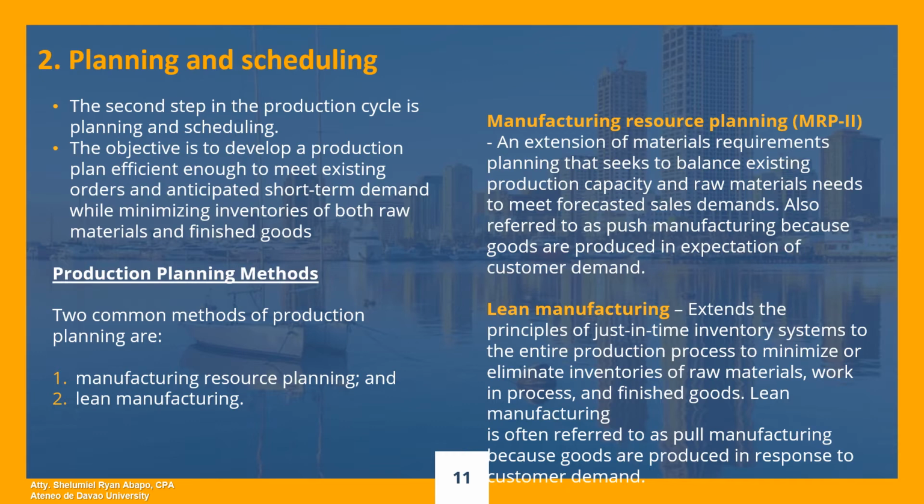However, in practice, most lean manufacturing systems develop what we call short-run production plans. Ano tong short-run production plans na to? These short-run production plans are developed on a monthly basis, which is the practice now of Toyota, so that it can provide a stable schedule to its suppliers. The strategy of producing monthly production plans enables now the suppliers to also plan their own production schedule so that when the manufacturing plant would now have to ask for the delivery, these suppliers can deliver their products to Toyota or to the other manufacturing company or manufacturing clients at the exact time that they are needed.